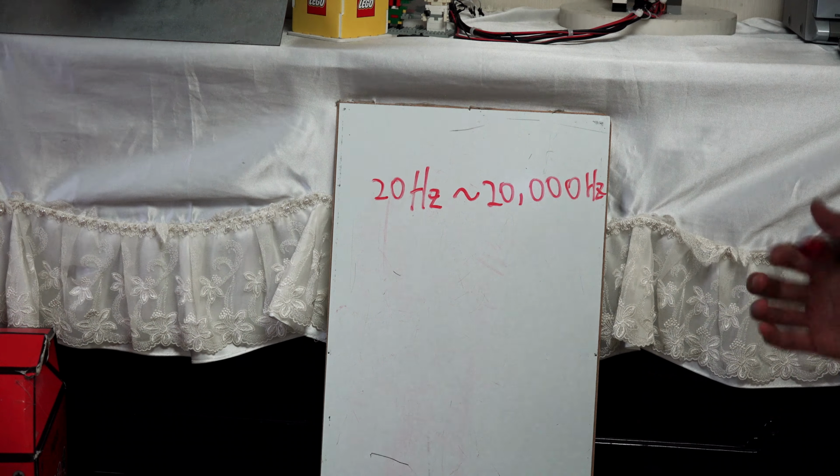So that's all. The distance is the duration divided by 29 and by 2. So it just means 58. So we can just find the distance by dividing the duration by 58, and it shows the distance.